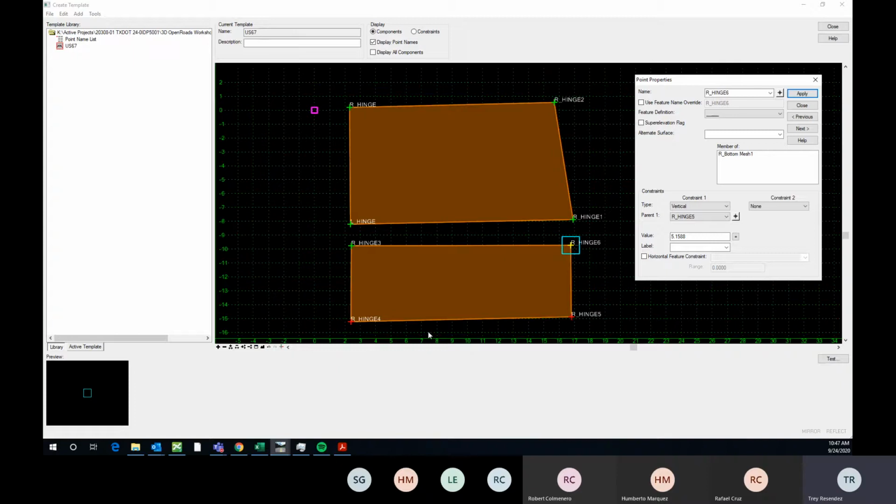And these are the three main point constraint characteristics that you'll see. You're either going to see green, yellow, or red. Green is no constraints, yellow is one constraint, and red is two constraints. So it's really important to know what these mean and how to use them.